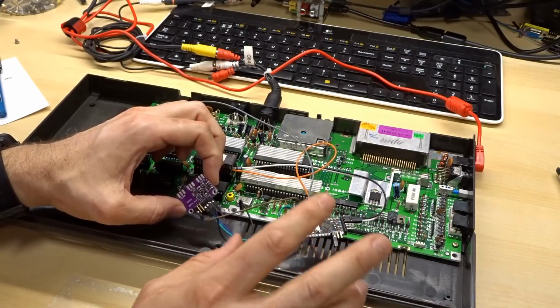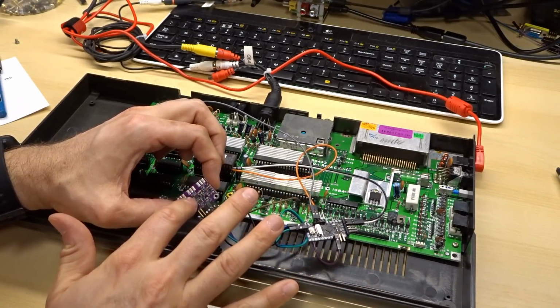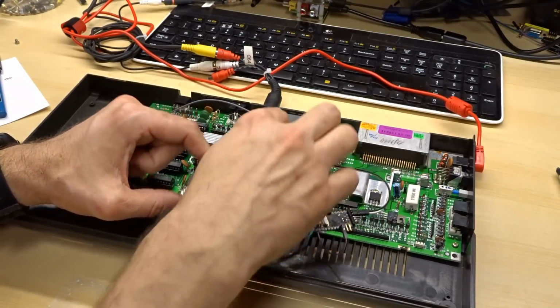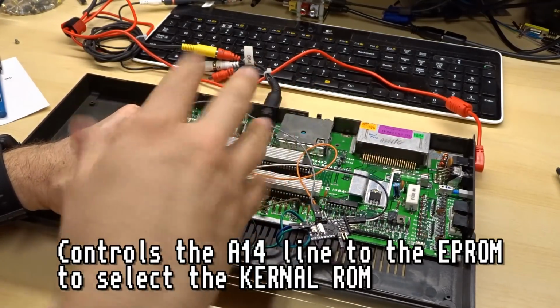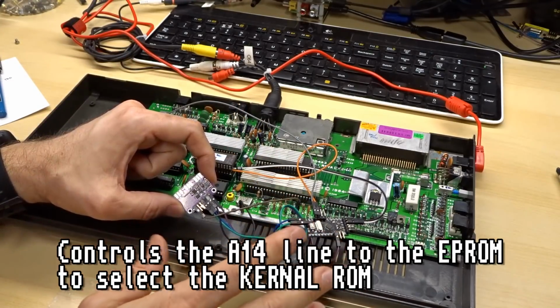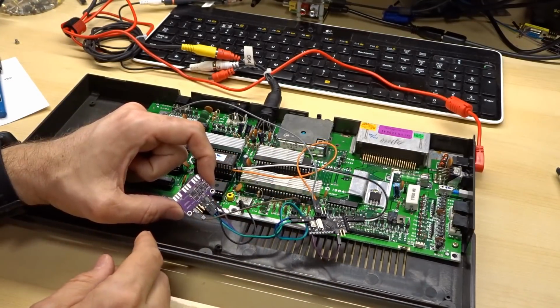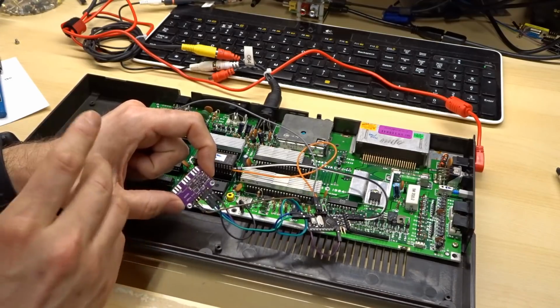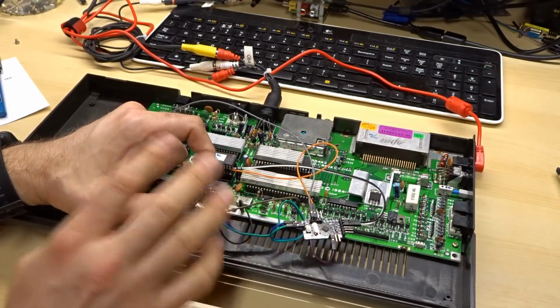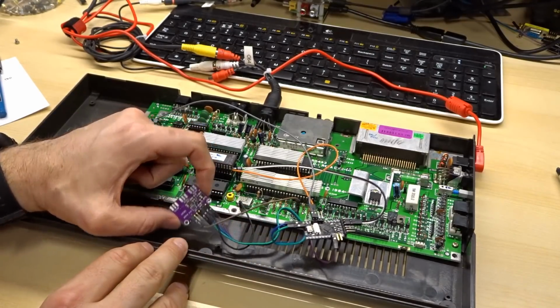So the first thing this thing does is it turns on and then immediately programs the clock to generate the frequency to run the machine, and it also pulls the address line high or low depending on what it needs to do. That all happens nearly instantly, and that's because of Optiboot. So I really recommend that if you're going to do this project, you also install Optiboot on your Arduino so that you do not have that lag time when you turn the machine on.